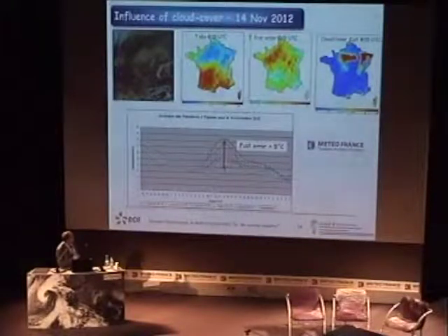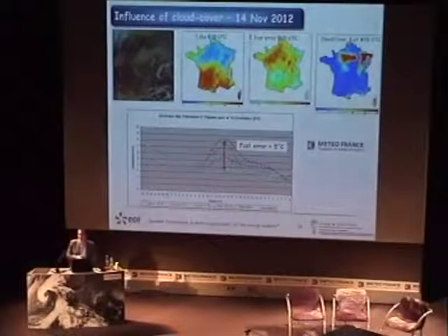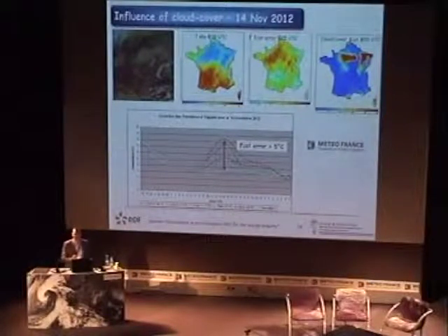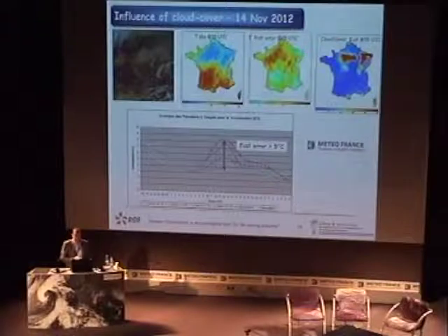And you can see that for only 6 hours lead time, we have a forecast error of more than 5 degrees. And 5 degrees is more than 10,000 megawatts error. So it's very, very important. And so cloud cover is really putting a lot of uncertainty on the temperature forecast. And of course, you can imagine that it will have a high impact too on solar production, either PV production or concentrating solar power too.